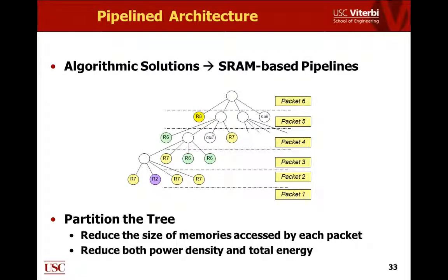So we are looking for pipelined architectures because a lot of our implementers essentially are doing something like this. There is some kind of a tree structure, trie or a tree is going to be used, and then we partition that and then map it onto the target architecture, and then we do the comparisons level by level, meaning that by pipelining it, we can get very high throughput by being able to, for every clock cycle, which corresponds to the amount of operation you do in a particular level of this tree here, push these packets at a very high rate through the system.